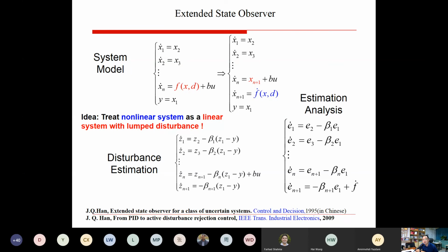In this case, all the control algorithms have a fair comparison because we have the same control saturation. But in most cases, we use what we call input shaping: we change the step reference into a soft one. We shape it like tracking a curve, not a step reference. Then in most cases we can avoid control saturation, because only in the large error case, the large disturbance torque case, will we have control saturation.